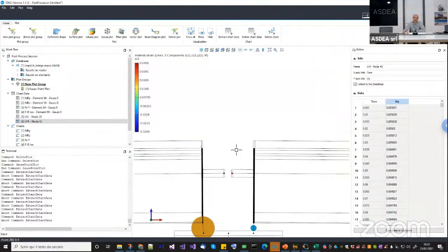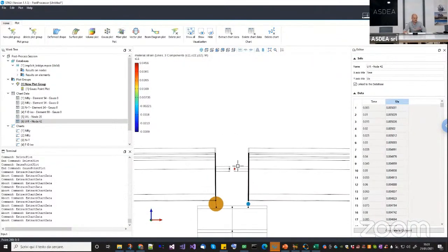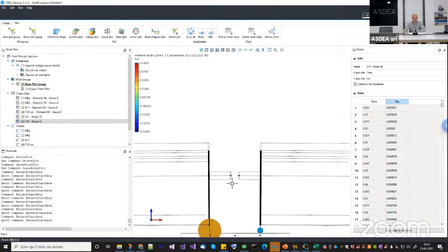Because every time you do a nonlinear analysis, it is a compromise between the complexity of the model, okay, and the speed of the analysis. So sometimes you don't want to include certain nonlinearities because they can mess up your model. Contact is one of them, and you assume that you don't need them.